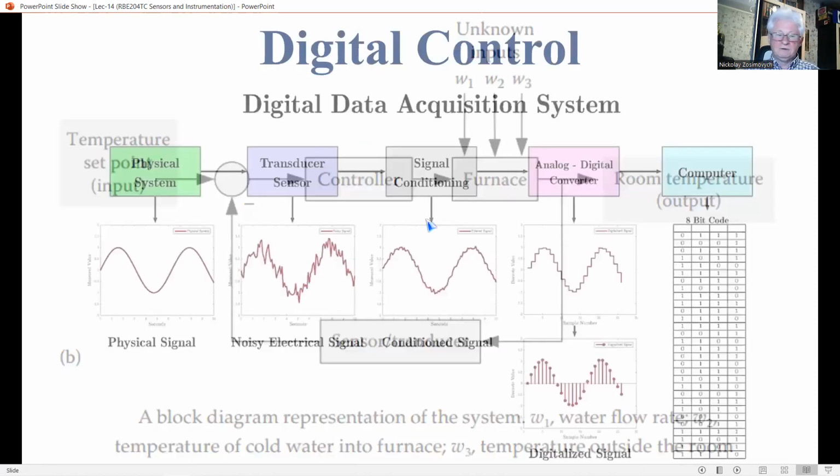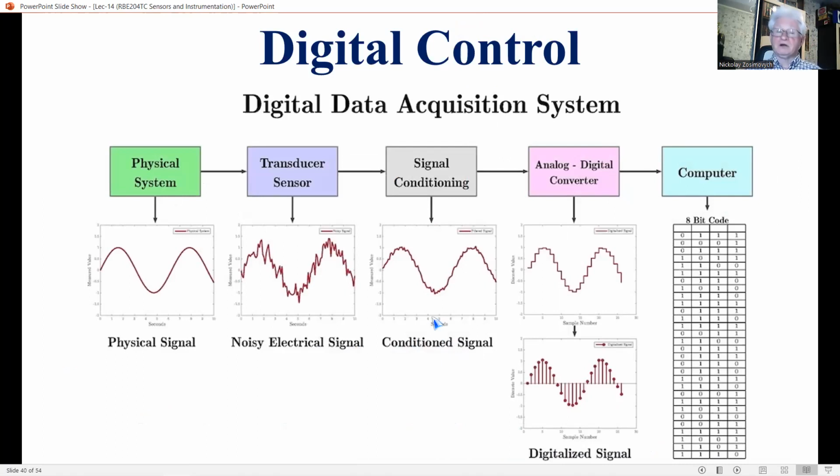In digital control, a digital computer or microcontroller serves as the controller. Virtually any control law may be programmed into the control computer. Control computers have to be fast and dedicated machines for real-time operation, where processing has to be synchronized with plant operation and actuation requirements. This requires a real-time operating system. Apart from these requirements, control computers are basically not different from general-purpose digital computers.